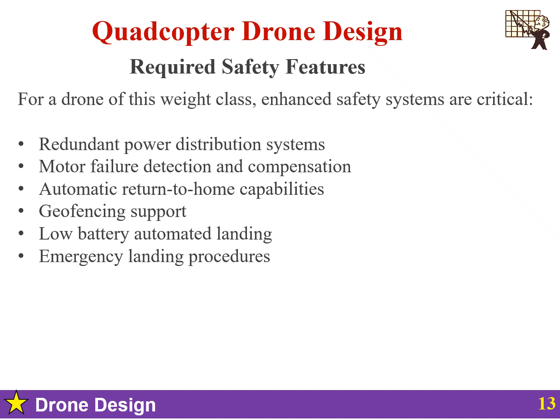And the last is telemetry and the black box. Professional operations require complete flight data logging, GPS track recordings, altitude and speed logging, battery performance recording, event logging for incident investigation. These aren't features, they are engineering requirements for safe operations of a 5 kg aerial platform.